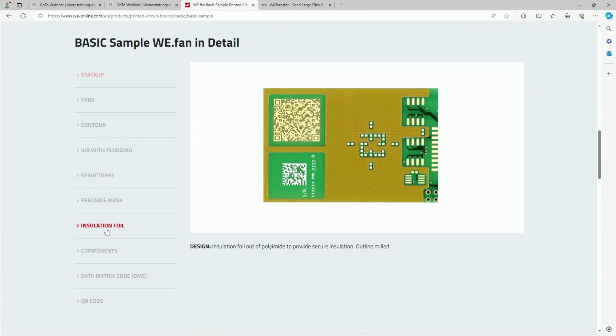It's the same material we are using in rigid flex technology. It's coverlay, a combination of polyimide and gluing film. The contour, the outline, is milled and then glued under vacuum to the surface. So this has a high breakthrough voltage, excellent isolation, and could be used to protect the PCB from contacts to the housing, maybe, or heatsink.